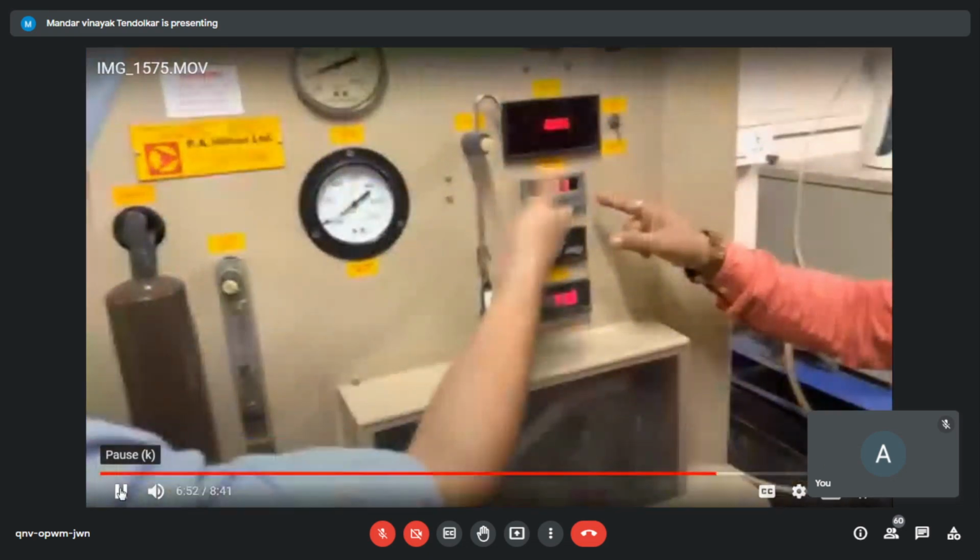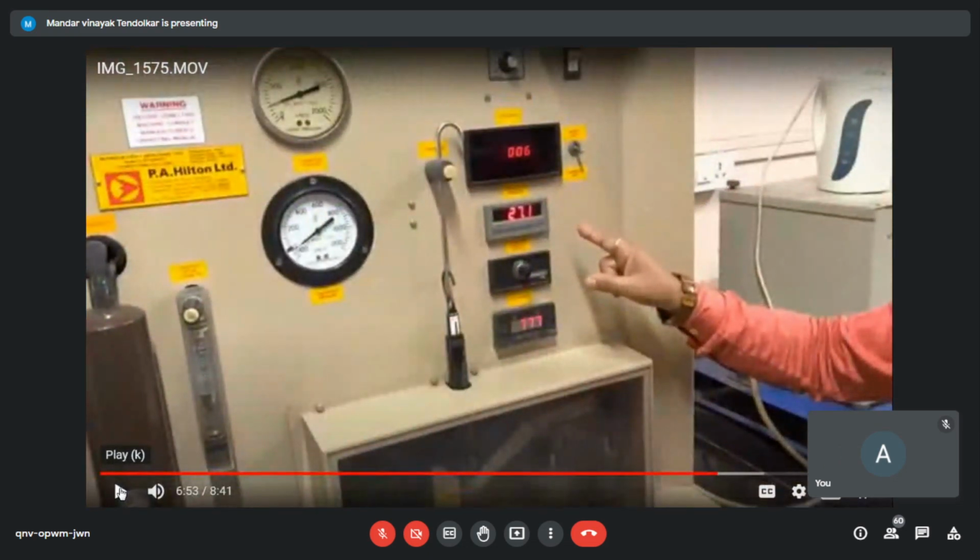T3 is after the rejection. So it has to be now again 27. T3 is after the water cooling, correct? Condenser, water cooling. So it came down again from 30 to 27. T2 is compressor outlet. That means condenser inlet, and condenser is water cooled. So heat got rejected from 30 and it comes back to 27. Correct or not?